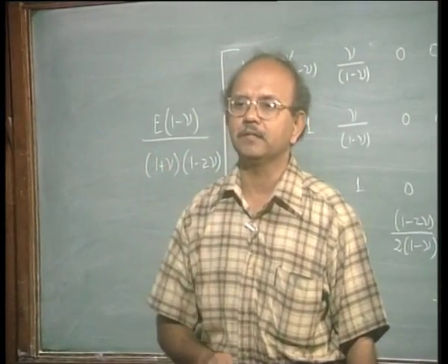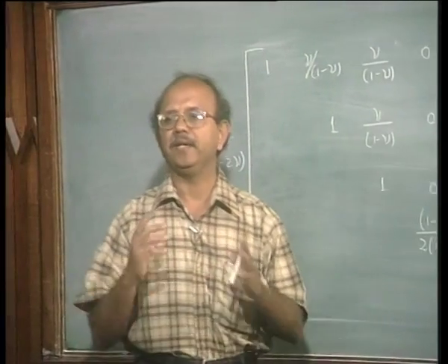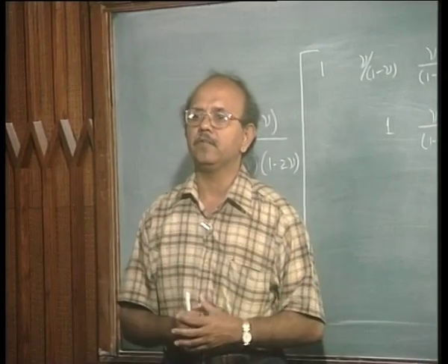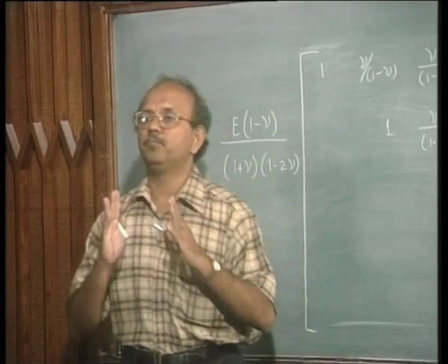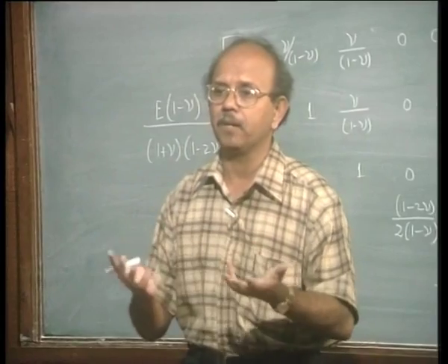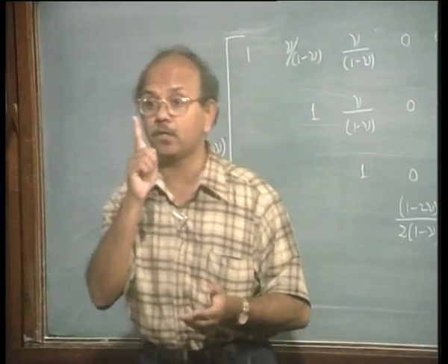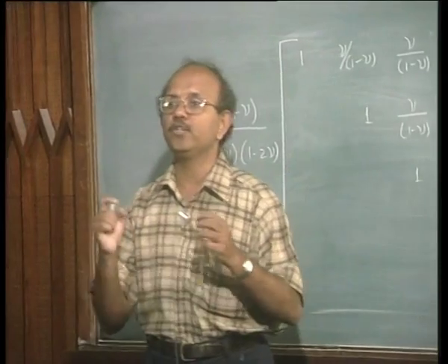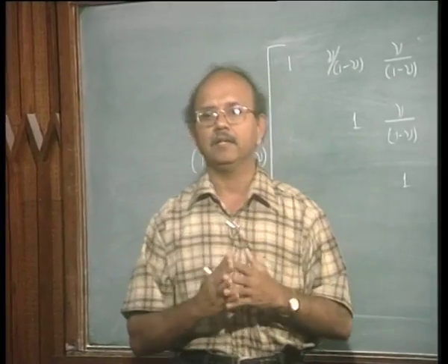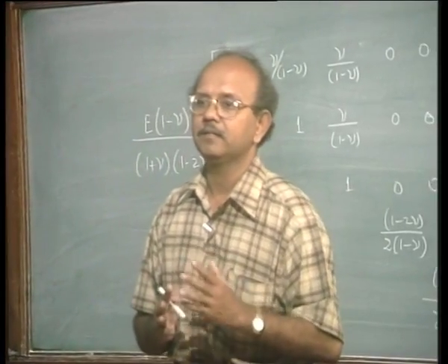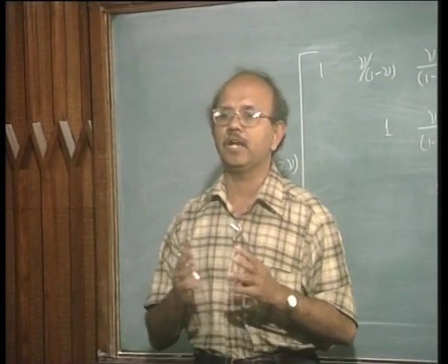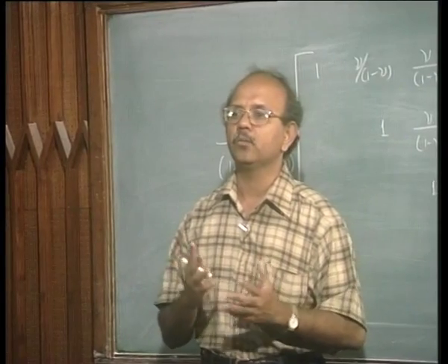The second one is that there are certain behaviors like bending. This bending behavior can be caught in a much better fashion by certain specialized elements like a beam element. Bar, please note, is not for bending, it is only for uniaxial loading. So you can catch the effect of bending very nicely in a beam element, plate element, as well as a shell element. These capture it very nicely.